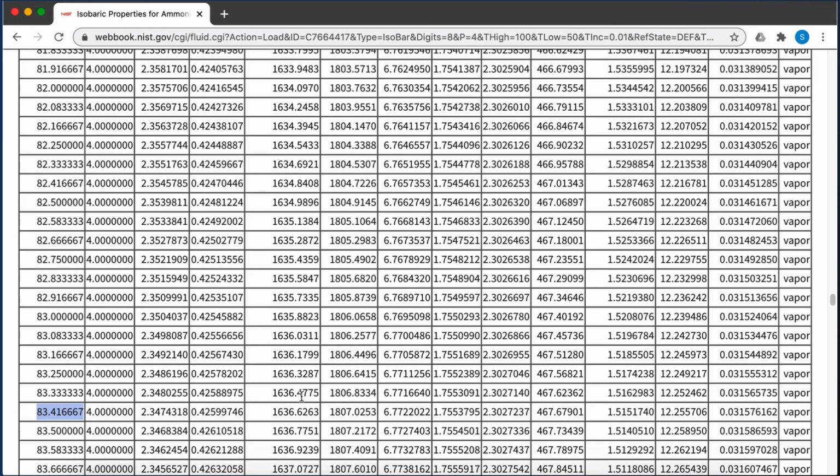So we were off by 0.1 Celsius, but all things considered, we've got a better uncertainty than 1%, and we used a different resource and had a totally different value for the specific enthalpy. You can see that physically, though, we got about the same temperature, and that was the point of this exercise. So again, when doing problems like this, make sure you don't mix and match between textbook values and NIST values. As long as you stick to one resource or the other, though, you should get the same physical outcomes.